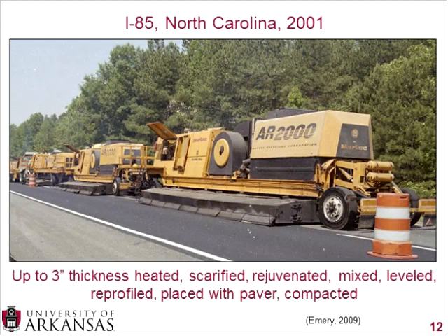And then finally here in 2001, we're in the next generation, or the most current generation of heaters. The heaters are a lot more sophisticated. Up to 3 inches of thickness of your pavement structure can be heated, and you can either scarify it or you can mill it up, rejuvenate it, you mix it, level it, reprofile, place with the paver, and compact it.